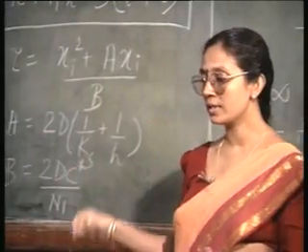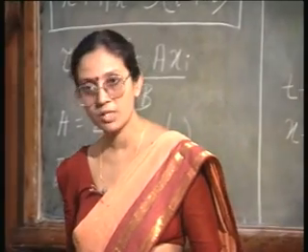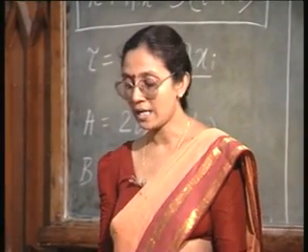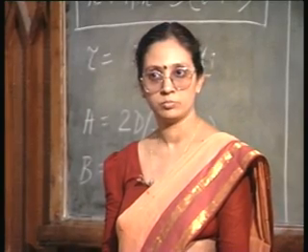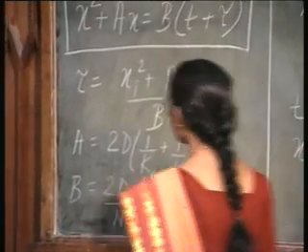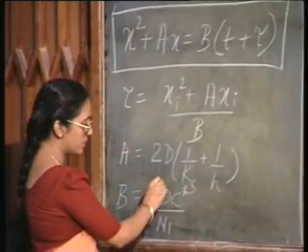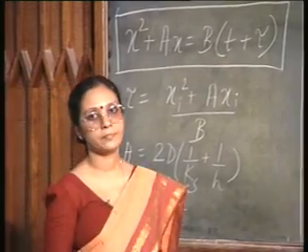At 920 degrees centigrade you have seen that B was 0.203 for wet oxidation, and at 1200 degrees centigrade it has increased to 0.72. This is an increase which can be explained by this diffusion coefficient D.